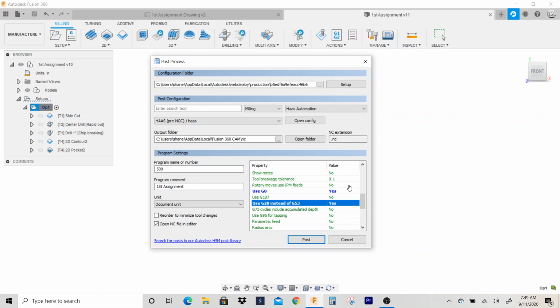The reason why: if you use high feed rate, it'll put in 500 inches per minute, okay? Now, in a typical setup process, you're setting up a machine and running a program for the first time. You want to slow down your rapids to make sure everything's right, so you don't come in and break a tool or crash into the part.